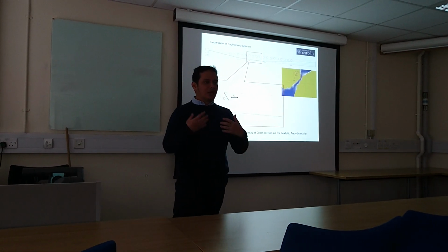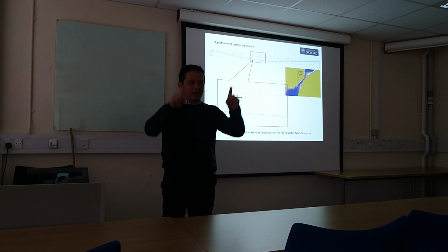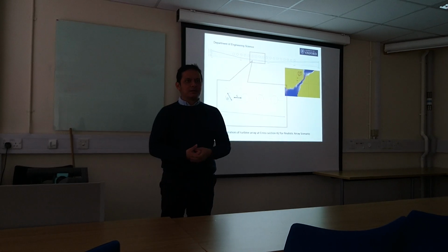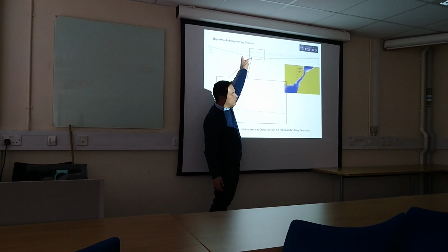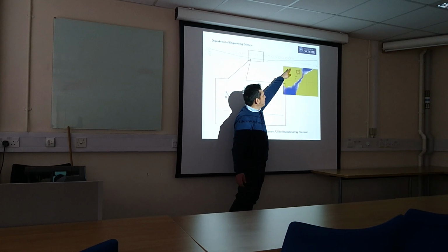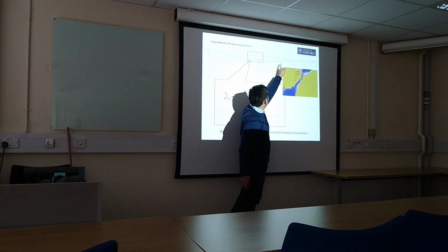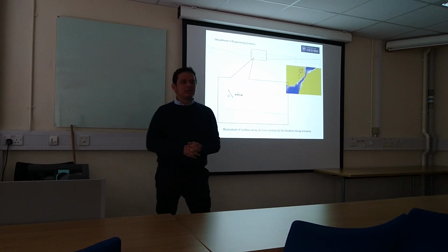And for 12 turbines, I multiply by the swept area of the turbines. I compare it again to the cross section of each element. So I apply that as a blockage ratio in this node, and then in this node I compare it with the next node. The average from this node and that node will become the blockage in this node. So this is how I do the realistic arrays in this.